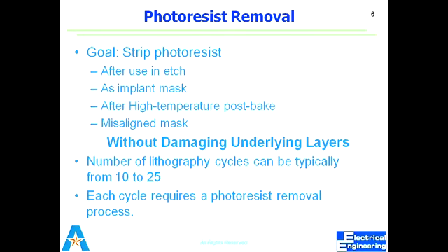First of all, the thickness of the photoresist should be more than the thickness of the thin film. Removing the photoresist, we usually use acetone, and developing means that only the sensitized photoresist would be actually removed by that developer. So if you have a thick layer of photoresist as compared to the aluminium or anything on the top of that, it should be metal. So when this is removed, it cannot stay in air, so it will also be removed.